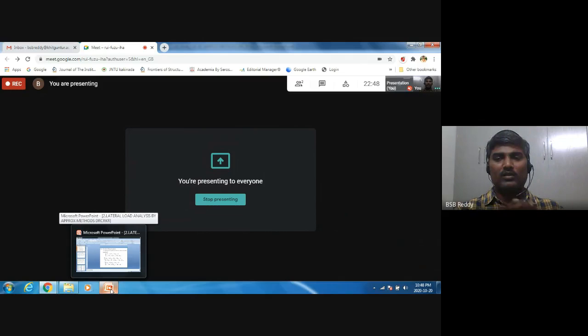Once you complete the column shear, the next connecting quantity is the column end moments. Step one is column shear. You know how you calculate it: by taking the section at the middle of each story and writing sigma Fx equals 0, you will get the column shears. Step two is multiplying the column shear with half of the story height, which gives you the column end moment value.